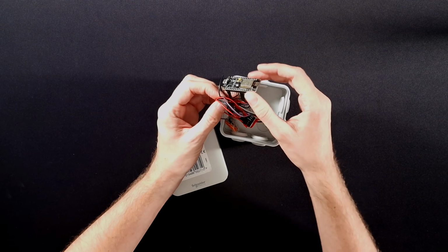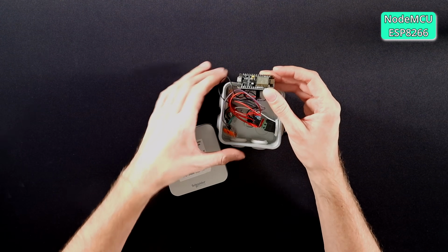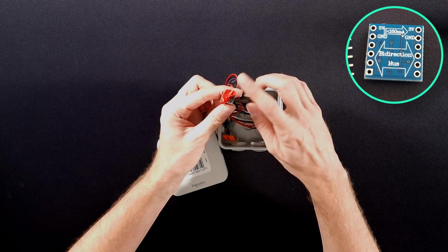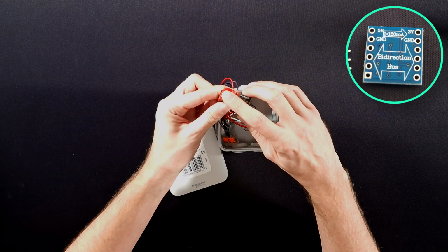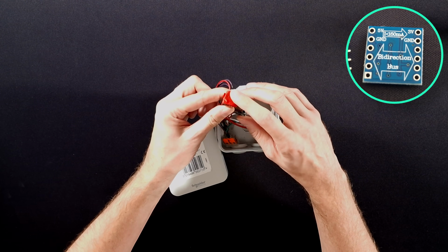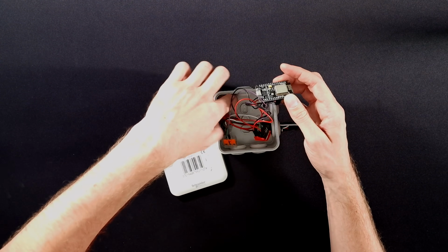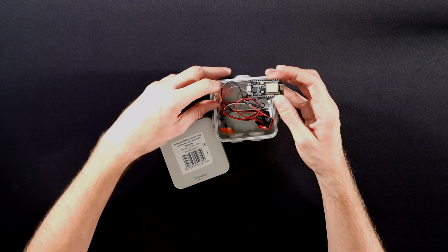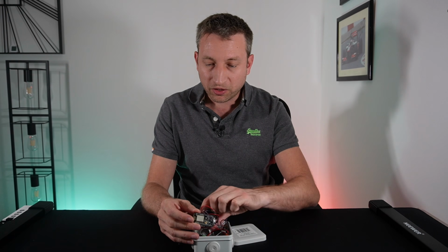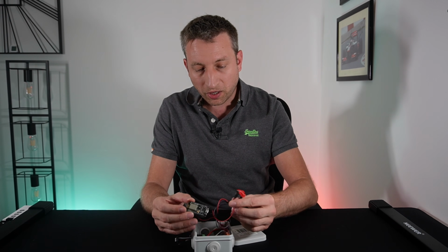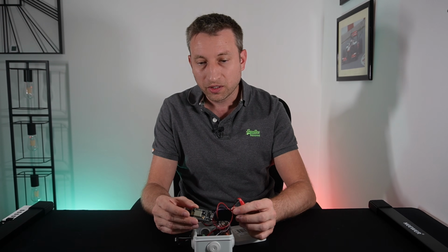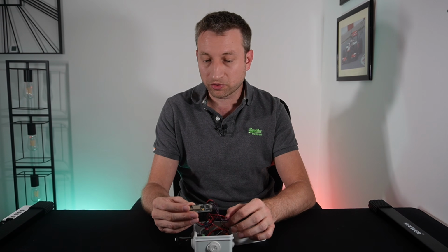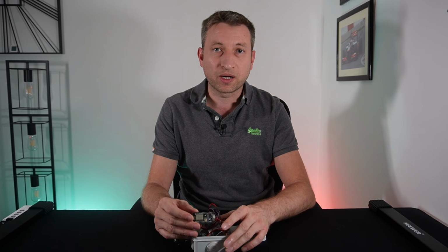And we can see here's the microcontroller. And here we've got the logic level shifter, which I've put just a bit of tape over so that if they touch each other, they don't cause an issue. And then some Wago connectors just connecting them together. And that's about it really. Because I've got the logic level shifter, I haven't included a resistor. A capacitor probably still would have been a good idea, but I've got a fairly good power supply, so it doesn't matter so much.